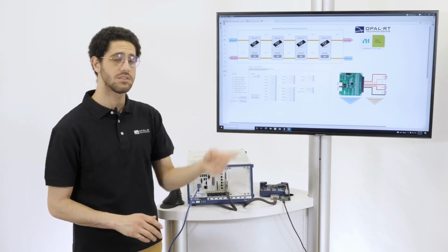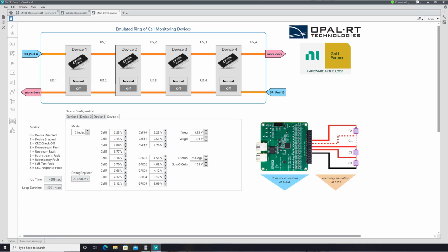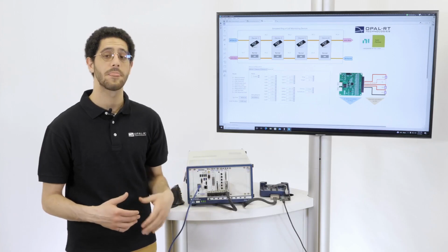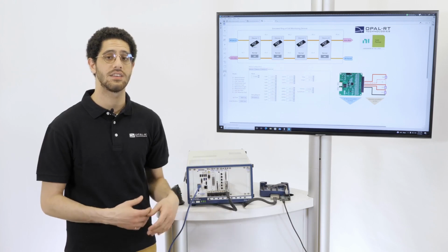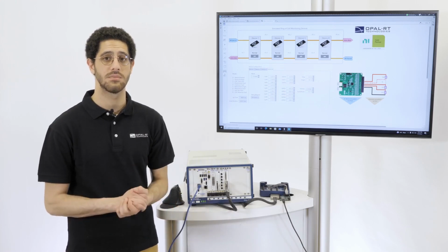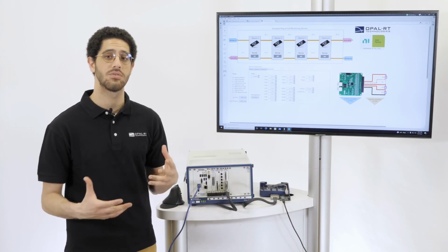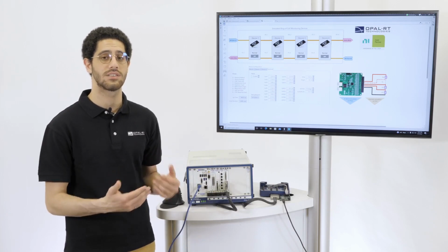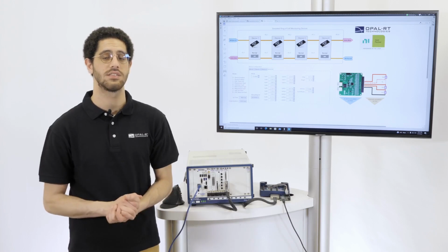We also have pinouts that allow you to connect to external LTC6811 chips, allowing you to mix a real hardware test along with a simulated test, or another FPGA that has an extended ring. If your battery management system is speaking to that many rings that they don't fit on one FPGA, we can always cascade different FPGAs together.